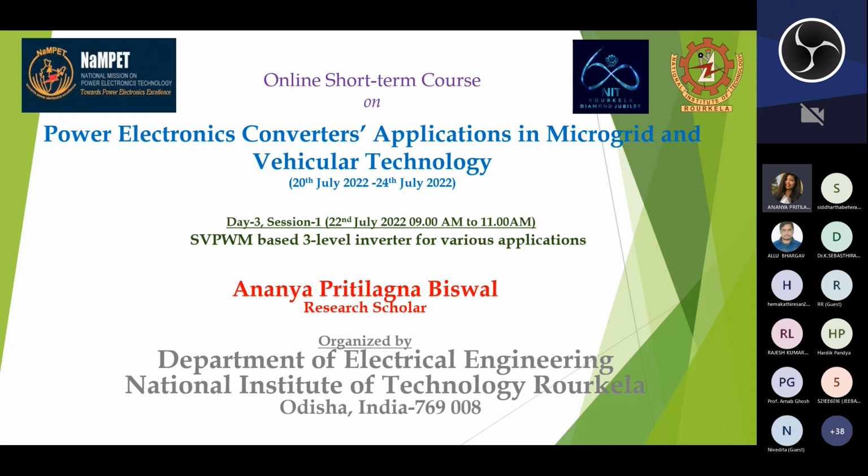Generally for a 3-phase voltage source inverter, because of easier digital realization and greater DC bus power usage, space vector PWM is now becoming more popular and practiced for controlling voltage and frequency as an efficient control technique. This work emphasizes the implementation of SVPWM on an induction motor in a step-by-step method.